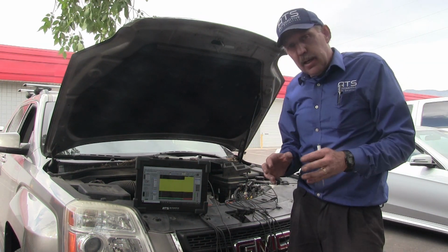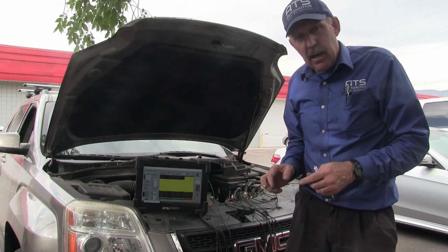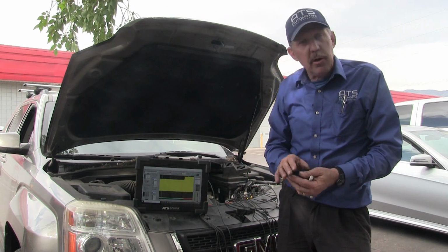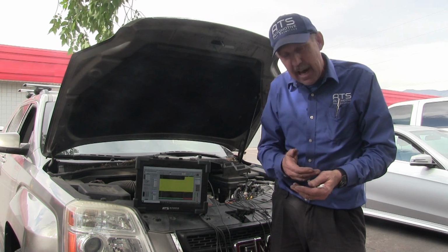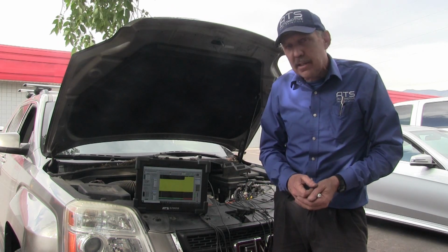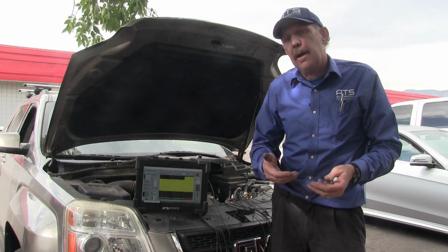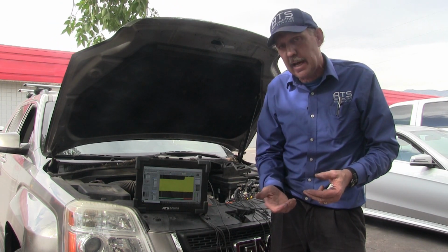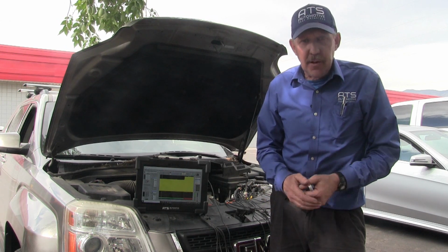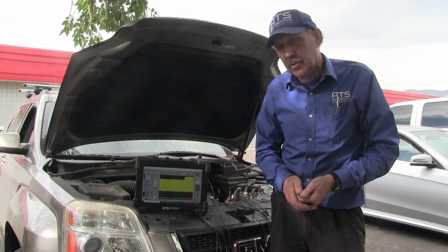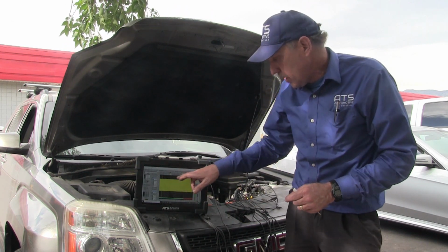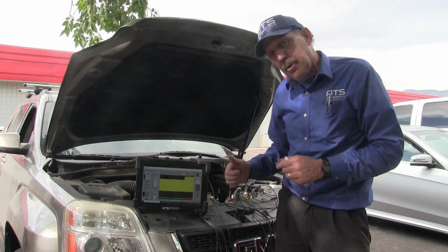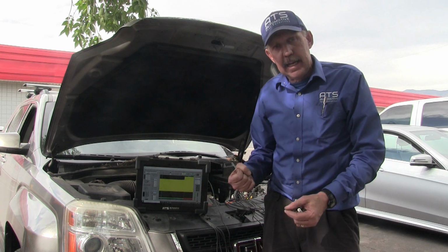What's happening is something's wrong with the ECM, and there's something on the board, or maybe an electrolytic capacitor leaks some acid and it's got a path. There's many different ways that a capacitor could fail and possibly pull a circuit down like this. Through the filtering circuit, there's high and low pass filters on these, but something is pulling on that circuit, and you can clearly see when I put the signal in and I disconnect it.